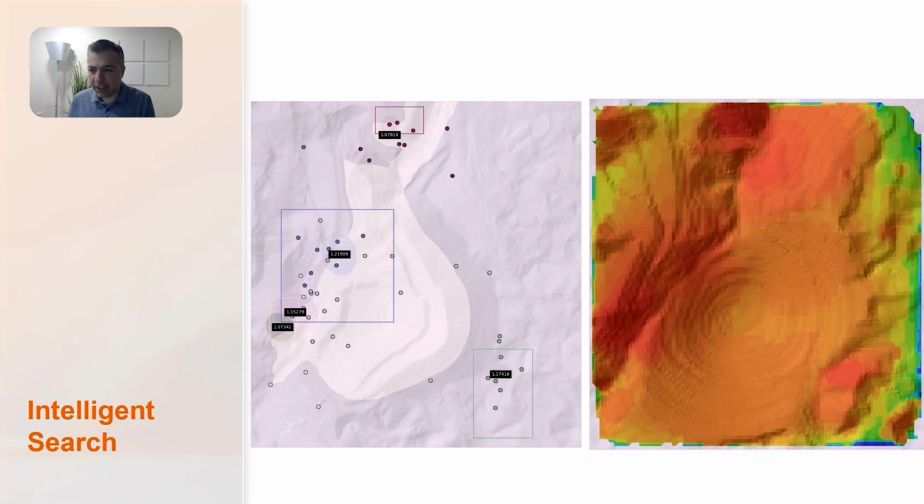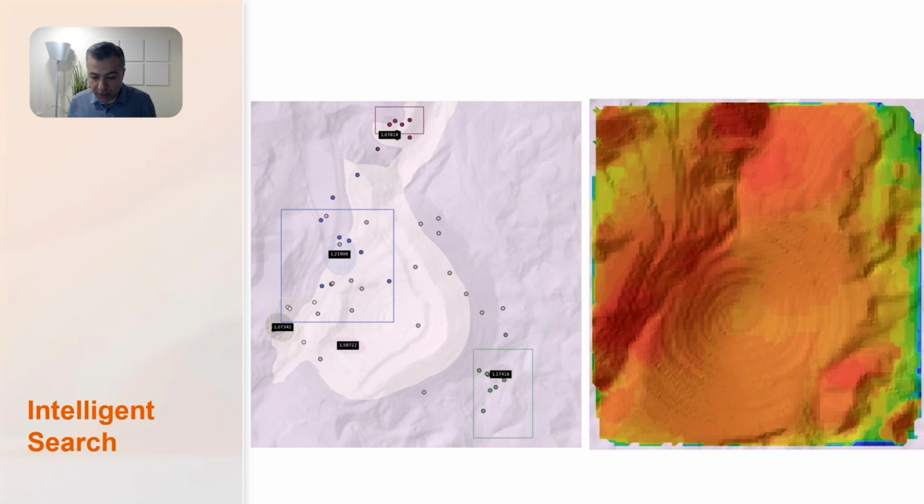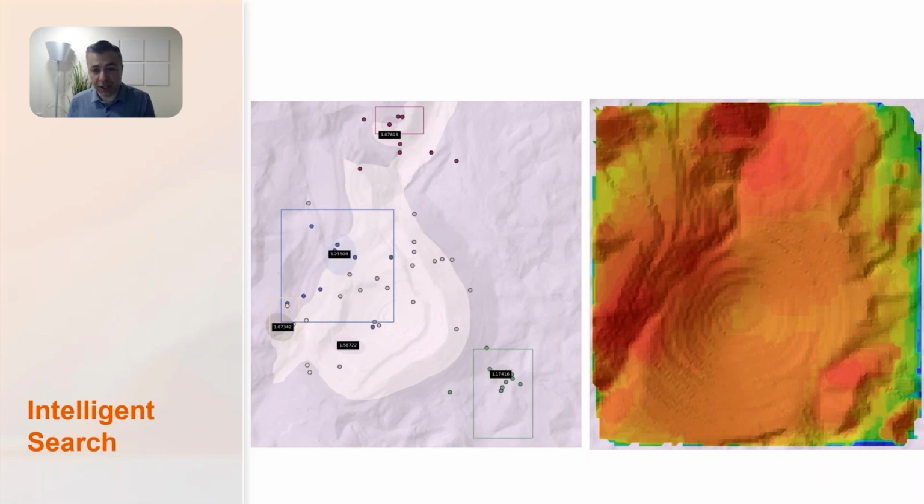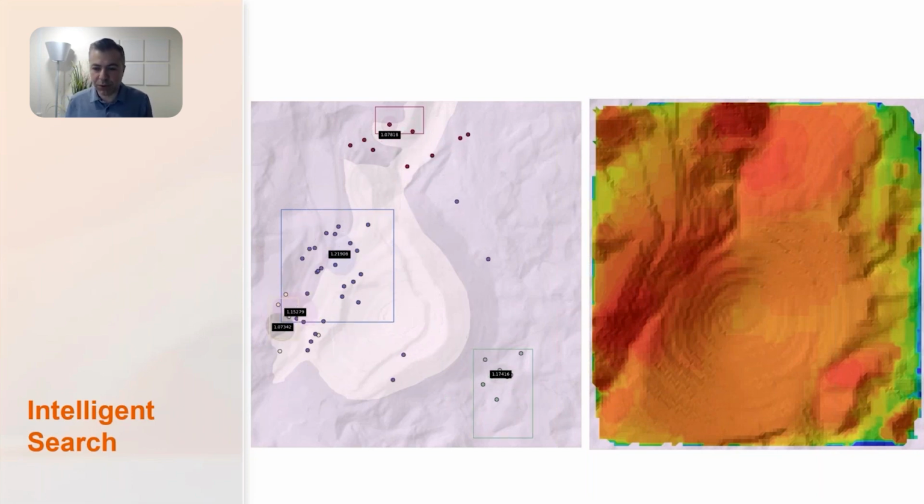The reason that I brought it here was a block model feature is mostly for big mining open pits. And if you create a model using block model, we do recommend that you use intelligent search because intelligent search is designed for those kind of models and to give you the most accurate results.